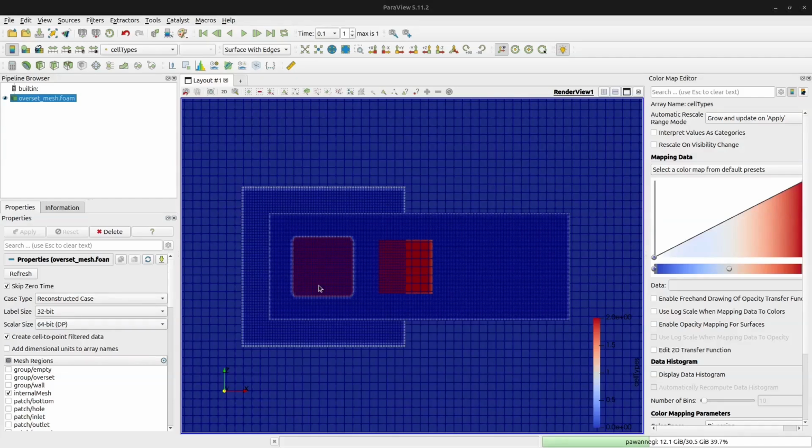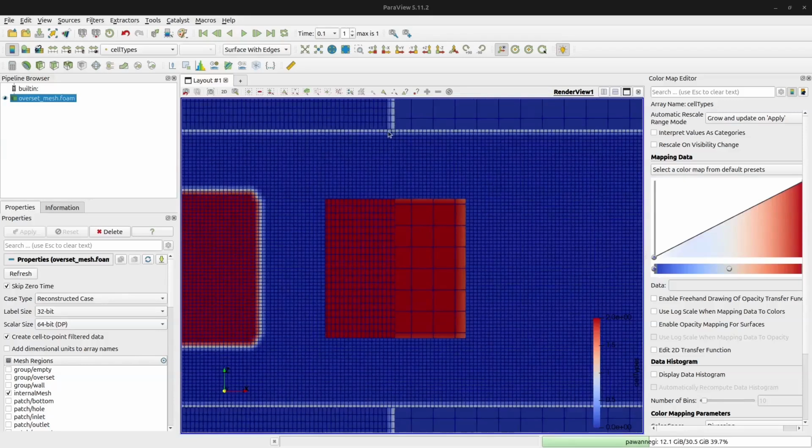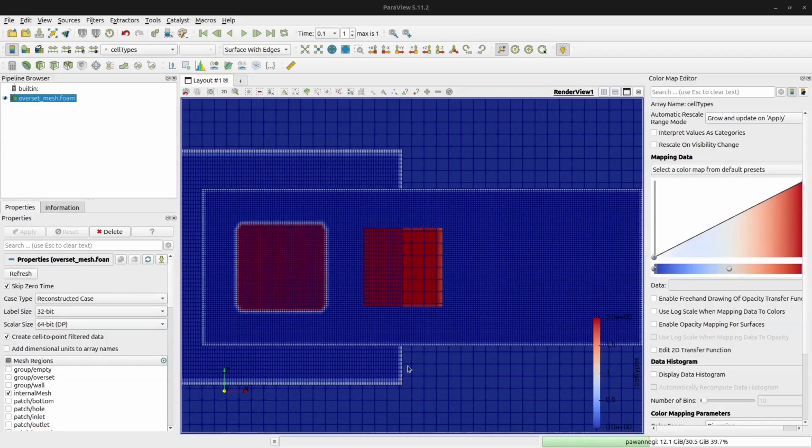If you go to the OpenFOAM website or any of the forums which discuss OpenFOAM, you can see that many of them will say that OpenFOAM does not work well with overlapping overset zones, and that is correct. You have to handle these special cases. For example, here there will be some errors, and this particularly small overlap will result in larger error over time. You should not rely on these kinds of results when there is an overlap. By default, it won't work. Make sure you understand this. With this, we can stop this particular lecture.